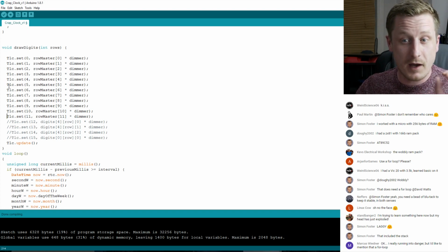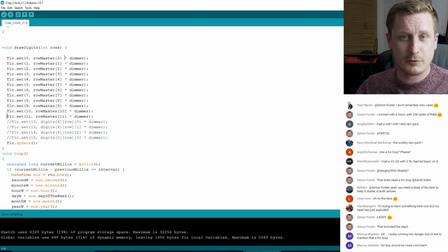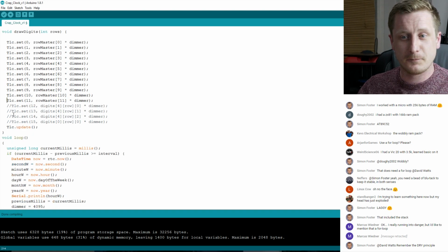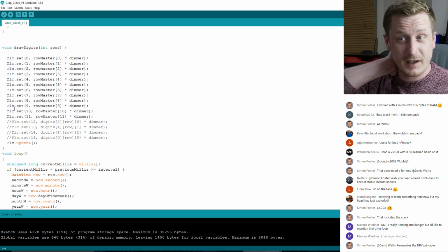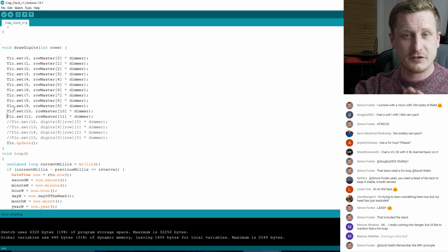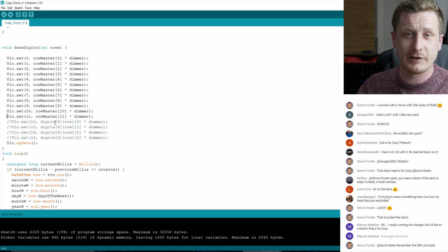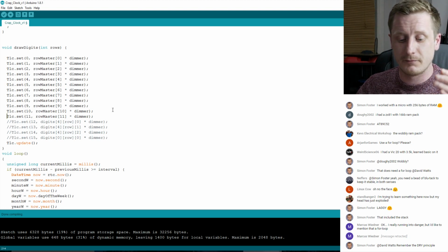not filling all the way, and I found out what that was eventually, but I wouldn't have realized what it was if it was all in a for loop, because it would just put all of those LEDs on, and I only noticed errors in some rows, not others, and it wasn't the beginning or the end, so a for loop wasn't going to help me at that point, and I'll explain what the problem was. So the TLC 5940 is like a shift register. You send it data and it shifts it along to all of its 16 different inputs. And the problem I had was that I wasn't giving it enough time to shift all of those bits in, or rather to adjust all of the PWM values on those inputs.